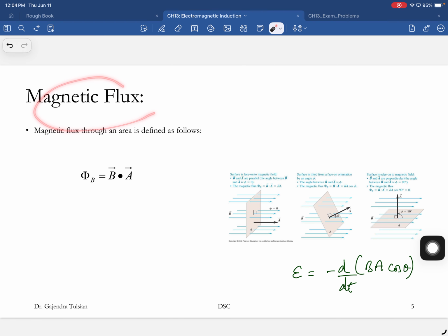So we define magnetic flux as the number of lines threading this area, and it's given by B dot A. So the magnetic flux is B times A times cosine theta. Here it's written phi, so B times A times cosine phi. If this were a loop of wire, the voltage induced in this loop of wire will equal the rate of change of this. And like I said, in practice, the easiest thing to change is the angle theta.